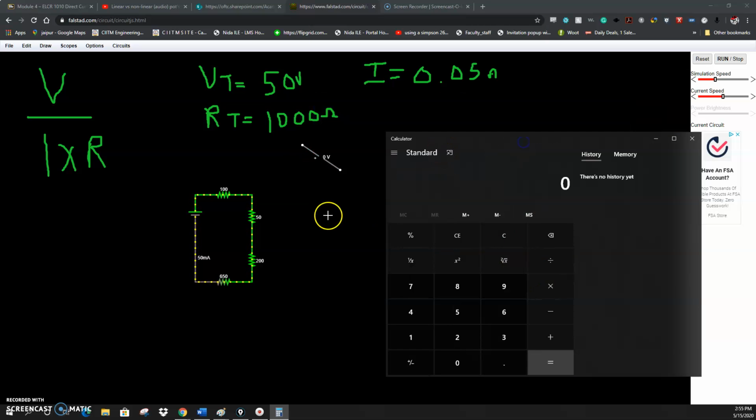So if we've got 50 milliamps of current going through this 100 ohms, it's I times R, 0.05 times 100 equals 5 volts dropped there. So let me get my mouse back, and I'm going to write it just inside here as small as I can, hopefully. And if I do the math on the next one, I'll let you do it, it's going to be 2.5 volts. And if I do the math on this one, it's going to be 10 volts.